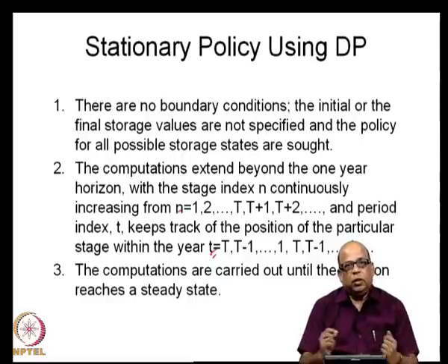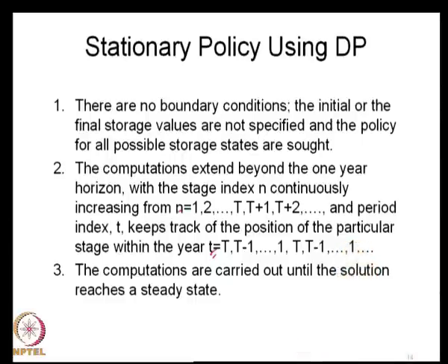So, essentially in today's class we started with the reservoir operation problem that we were discussing in the previous class. We introduced the multi reservoir systems where the continuity equations or the mass balance equations we write taking into account the controlled flows that come from the upstream reservoirs, and also taking into account the intermediate catchment flow at each of these reservoirs.